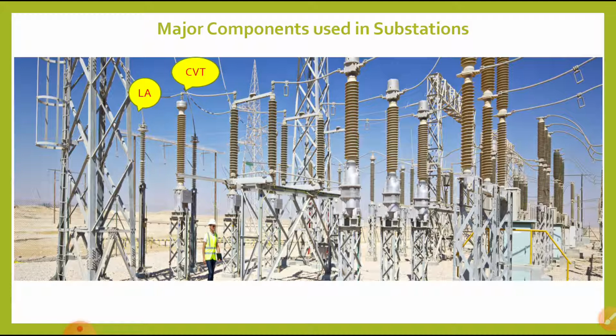These carrier frequencies, maybe 100, more than 50 Hz, don't enter our transformer windings. To avoid that, we use a wave trap and CVT. This combination is used to communicate with nearby substations about the load demand, whether we are going to shut down load or operate the breakers, so we can communicate easily instead of using telecommunication lines.